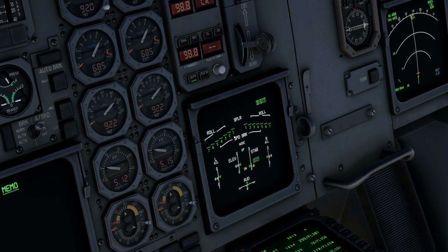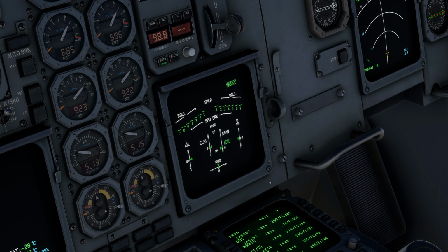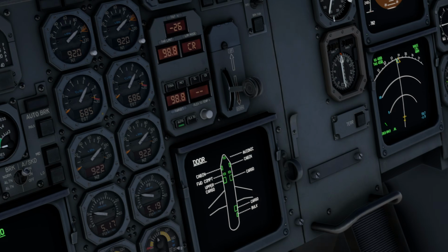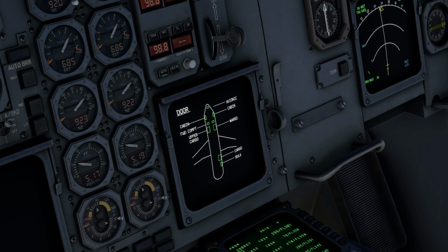Next to the flight control page, again an interesting page to monitor throughout the flight to make sure that all the flight control surfaces are distributed in a way where we would expect them to be. For example, if our airplane had a bird strike and has got some physical damage, then we might see the ailerons constantly slowly deflected or stuff like that. So, good idea to have a look at the flight control page to see in what kind of status your aircraft actually is.